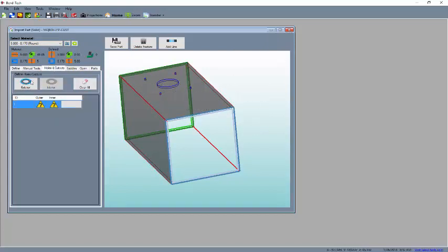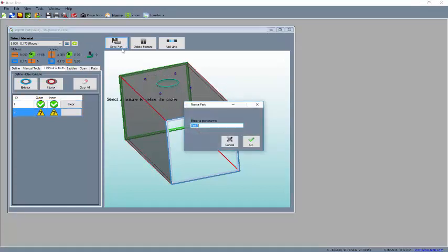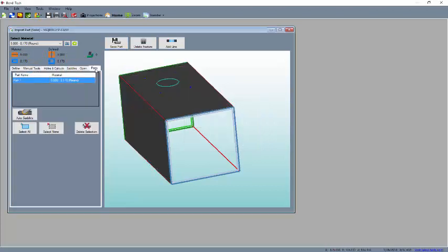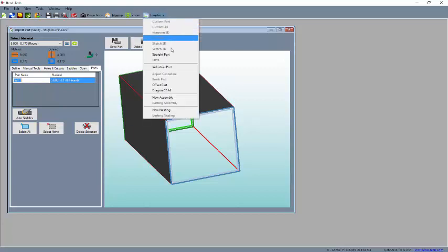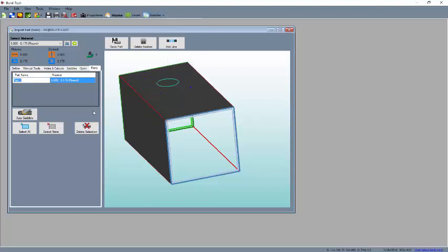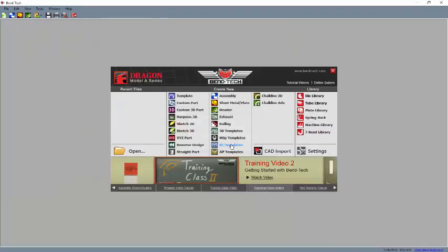Then you can go to holes and cutouts and define your holes the same way with exterior and interior profiles, and save those parts, add them to the parts list here, and in turn you can transfer those either to the CAM side of the software to get a flat layout and cutout, or to an assembly in this CAD side of the software where you can add to it, build off of it, and so forth. So those are options for you.